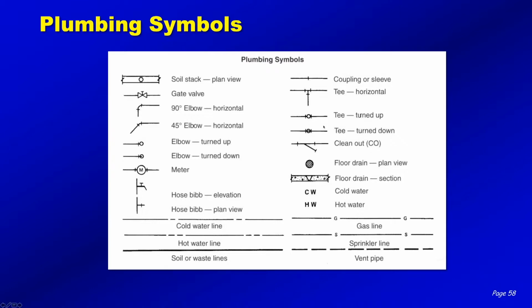Now here's one of the things I find gets people into trouble sometimes. They look at some symbols on an exterior site plan drawing, and they might see something that looks like, oh, maybe something like this. And you've got to make sure they're looking at a plumbing drawing, because it might be something else on an electrical drawing. So make sure that you understand the symbols that go with the type of drawing